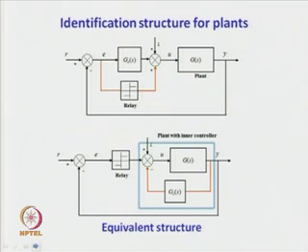So, let us go back to the identification and see why we are getting a symmetrical limit cycle output from the new online identification scheme. To understand that, let us consider the block diagram once more. R is the reference input, E is the error signal to the controller, and also E is the error signal to the symmetric relay. Now, when we have the relay in parallel with the PID controller or the controller GC(s), then the equivalent diagram or structure of the same can be drawn in this form.